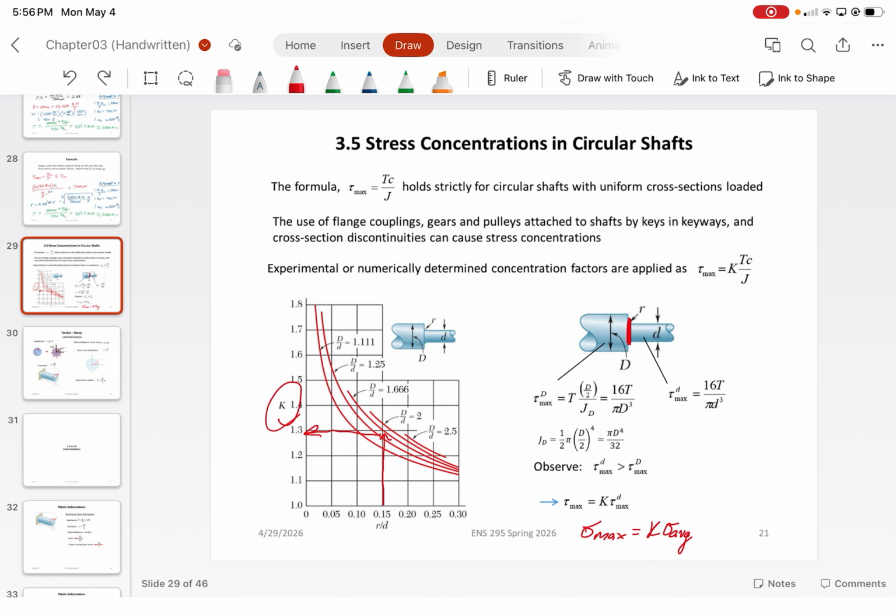And the reason for that is because this table or this analysis ultimately assumes that the torque within capital D and lowercase d are the same. Is this true? Again, it's very problem specific. You would need to perform the analysis to validate that the torque in the larger portion of that rod is in fact larger or not.